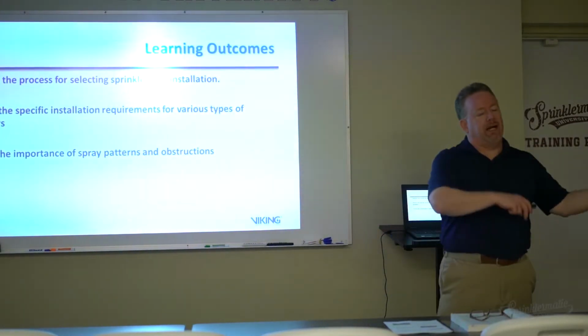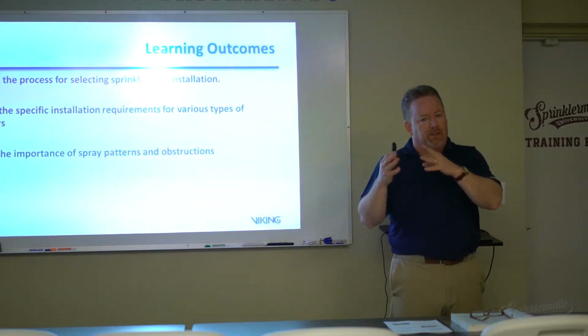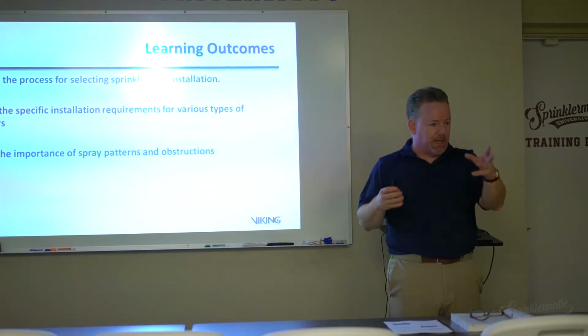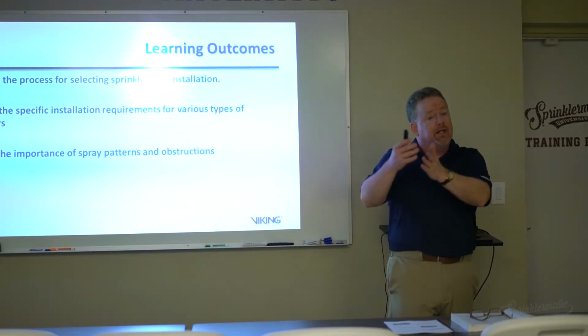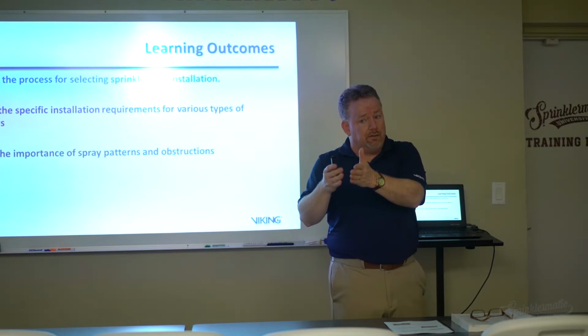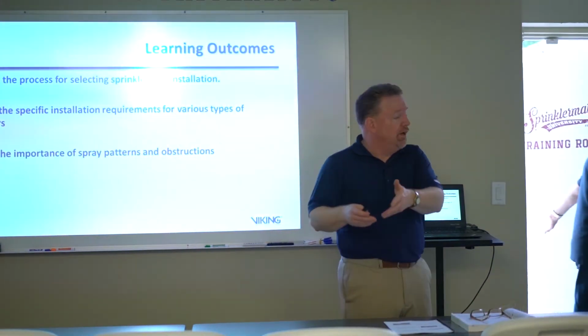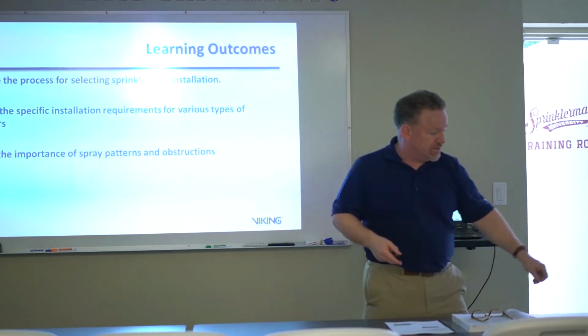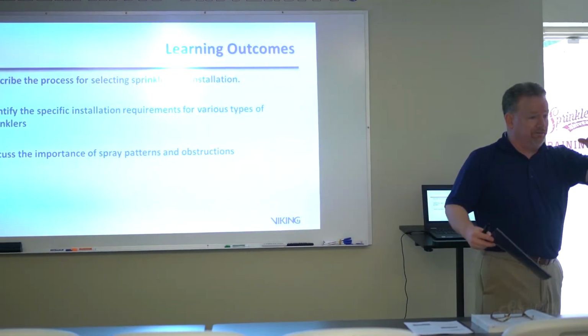So what usually happens, if there's going to be any question, a lot of times what designers or engineers might do on a building like this where they're not entirely sure where it's going to go, is sometimes you may consider over designing. Go with the 0.15 over that particular hazard area, so that you can fluctuate down.